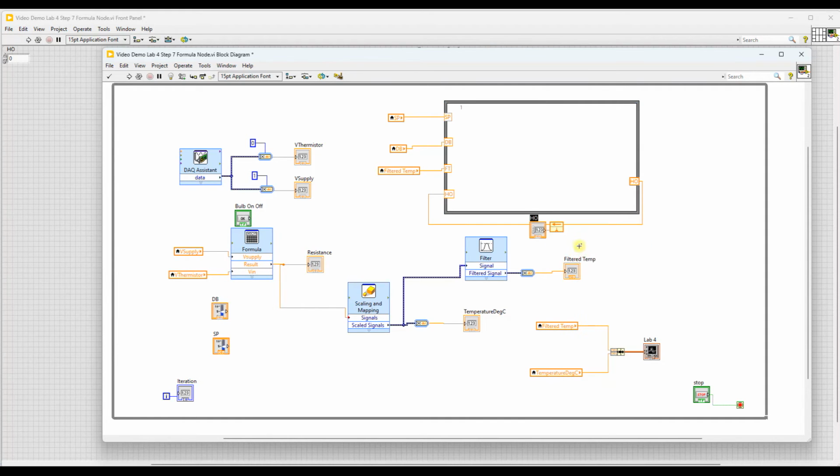I'm going to right click on that and put control there. And actually I want it to be a constant. I want it to be 0. So I'm going to delete that, and then control B to get rid of errors, and then connect that. All that does is that when the program starts, the heater output equals 0. Now let's start writing my code.